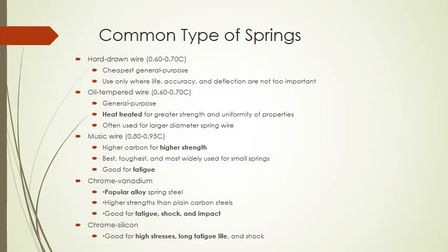Spring is a very important machine element, so in material science much research has been conducted on the use of materials for springs. Mainly it has a good fatigue life, and it has linear properties. It means when you use the spring, the load deflection curve should show a straight line. It should not deviate. So for maintaining these properties, you should have a material that remains in the elastic region, and you should have proper stress strain curves.